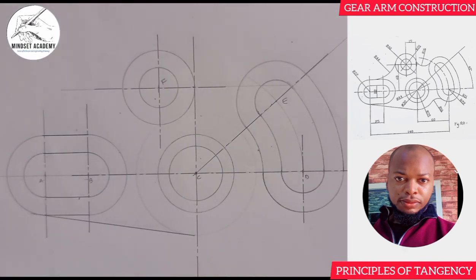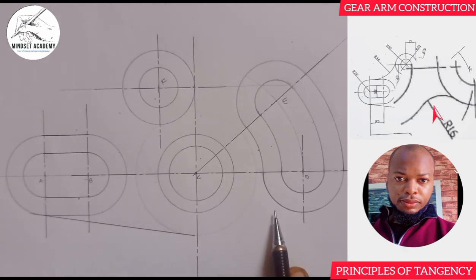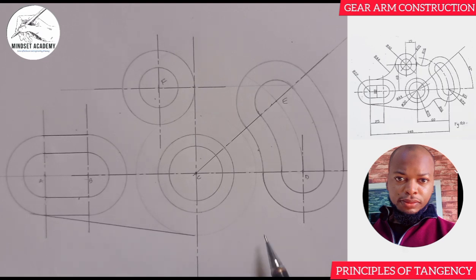So once you've done that, then remember that there's a circle here. So our circle has a radius of what? A radius of 35. And whenever you see a curve going in where my arrow is pointing, it's like a hole, and every hole you want to fill. So filling means you are adding. So we are going to add the radius of that circle with the radius of this. And that will be what? 16 plus 35. That will be 51.